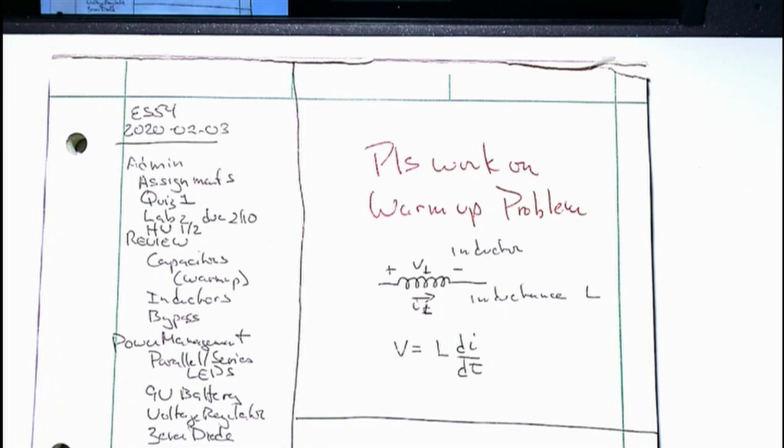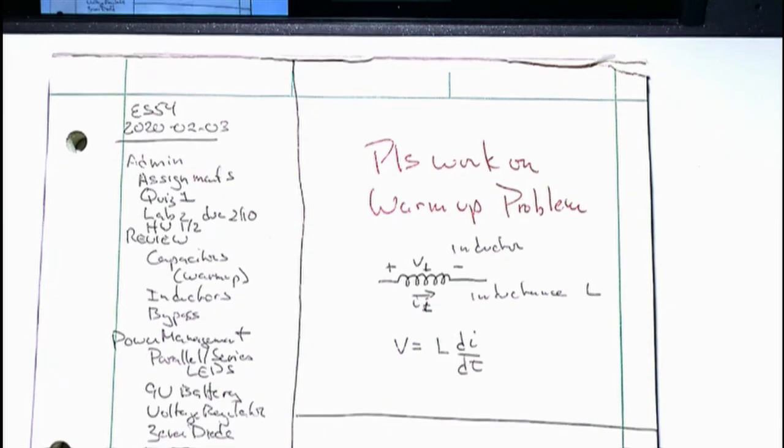We don't use inductors, and the reason is it turns out capacitors work better. They have fewer errors at the frequencies we're using them. At higher frequencies, you can't make capacitors small enough that they're very useful, so you use inductors there. But it's worth knowing about inductors. And inductance exists in any wire, but the more it has coils in it, the stronger its inductance, which, by the way, is measured in henries.